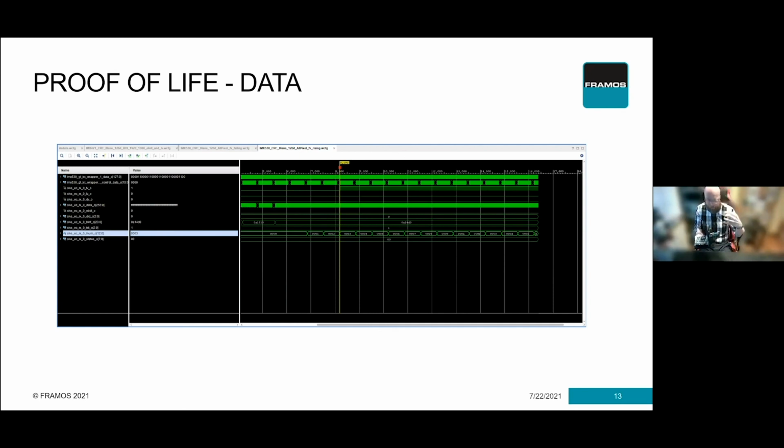And so, especially with the configuration changes, I always use a known working version here, and I try to recreate the issue that a customer may have. So, for example, this is an IMX535. If you're working on an IMX535 or similar sensor, and there was a bug, I'd ask you to send me your register set whilst you go away and do the foundation pin strapping all the way up kind of testing. You can give me your register set, and I can throw that register set at known good hardware. And if this has the same behavior that yours does, or similar, because again, I still have an observation issue looking through Sony proprietary hardware, we can then make some estimations and narrow down that problem.